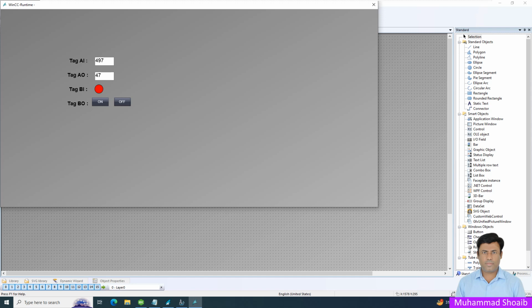We know already that WinCC SCADA supports the Modbus TCP protocol. So the purpose here is just to teach you how you can easily test in your work environment Kepware server and WinCC server, how you can exchange multiple data, and you can configure any type of protocol inside the Kepware server, and you can fetch data in here.